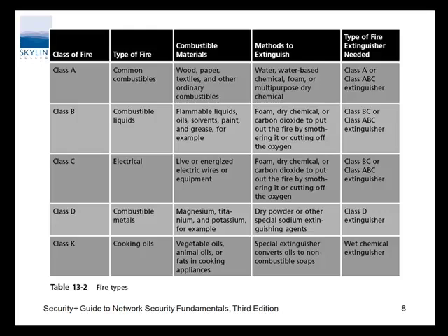An electrical fire probably isn't going to have a lot of smoke. And for this one, live or energized equipment, they say foam, dry chemical, or carbon dioxide. In my opinion, this book kind of contradicts itself, because in the previous slide we said the firefighters went in and sprayed this computer with, and what do they say here to use? Be careful which dry chemicals you use, because it is corrosive and it will destroy the insides of the IT equipment.